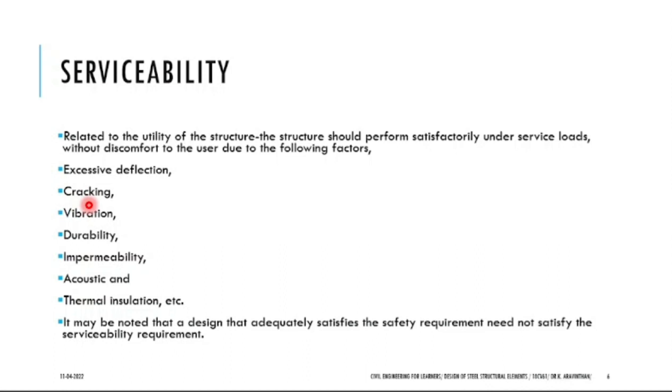When you take cracks into consideration, there are structural cracks and non-structural cracks. See, certain cracks can be healed by painting itself. If you apply a second coat or third coat of paint, they can be filled by paint alone. But certain cracks will not go even if you paint. You have to do plastering. That is non-structural cracks. Certain cracks are environmental cracks, which might be due to alternating heat and cold. If you place mortar again, it might be fixed.